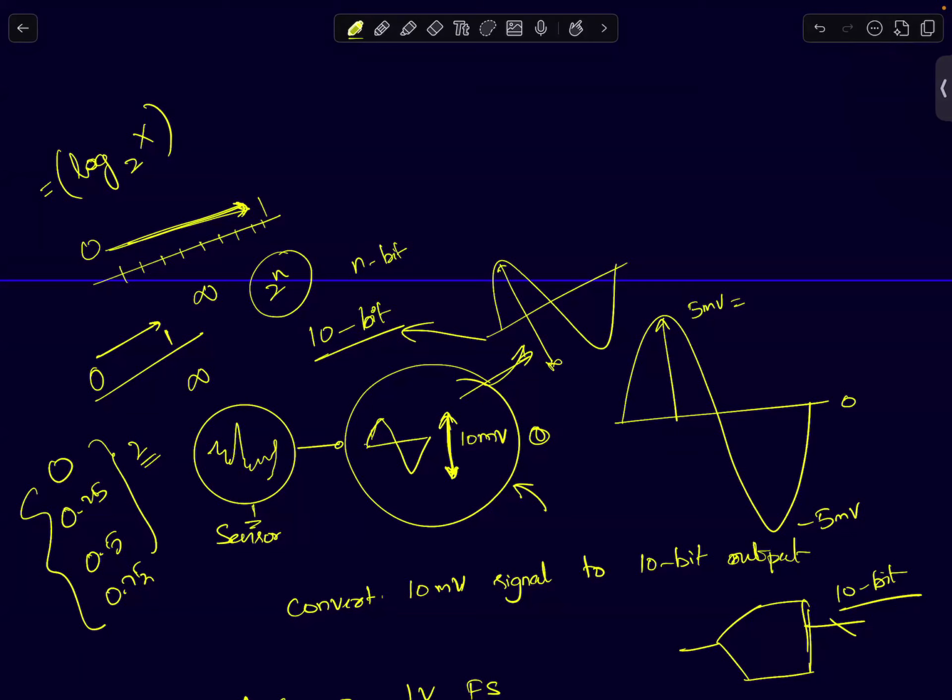So I'm telling you that to do that processing, it needs to convert real numbers to digital numbers, binary representation, if you want to do it digitally, right? Addition, everything we know how to do digital addition using digital bits. So I'm showing that if you have to convert this into n intervals, then you need log to base 2. If I divide the real numbers in the interval 0 to 1 into 2 power n intervals, then I can represent them using n bits.